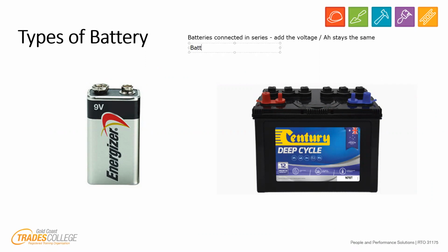Batteries connected in parallel. Total opposite. Voltage stays the same. This time your amp hours add up.